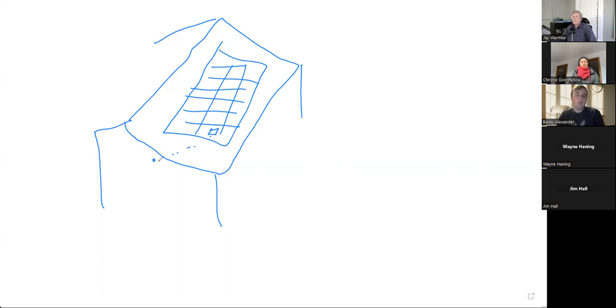There we go. All right, so I'm coming down here. Well, what's the next thing I go to is going to be my combiner box. So I'm going to connect in here to the combiner box. From the combiner box, I'm going to go to an AC disconnect. From the AC disconnect, I could just connect straight into that at the meter to this double pole breaker here. And I've never had to go inside the house. I never had to penetrate. Well, I had to go into the attic to do that.